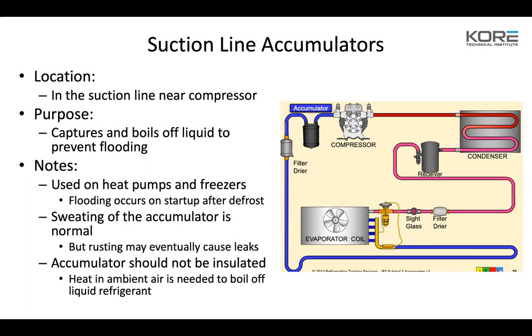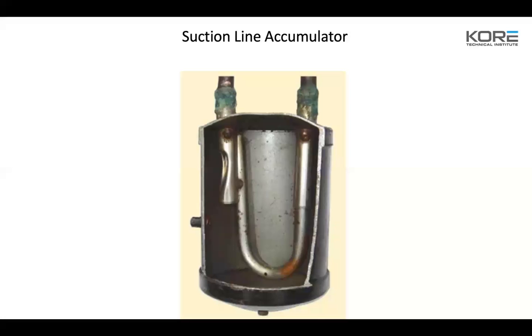The reason for that is it's kind of like a fudge factor component, to where if in your off cycle, or if you're shutting down the system in defrost and you're not pumping it down, then that coil is going to have a lot of liquid refrigerant inside it when it comes out of defrost. And when that suction valve opens up out of defrost and it starts flowing refrigerant again, there's going to be quite a bit of liquid coming from the evaporators to the rack or to the single system. And that's eventually going to knock the oil out if you don't have an accumulator.